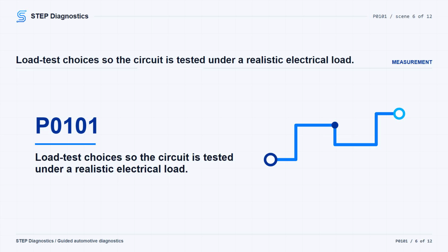Conductor sizes 24 gauge, 0.5 mm, or smaller are generally used to carry approximately 1000 mA, 1 ampere, or less, while conductor sizes 20 gauge, 0.8 mm, or larger are generally used to carry 1 ampere, 1000 mA, or more. For circuits carrying more than 1 ampere, load the circuit with a device that requires similar current. For higher current circuits, use voltage drop.